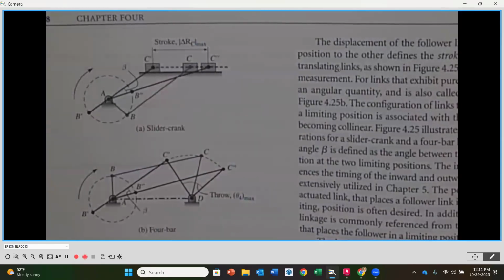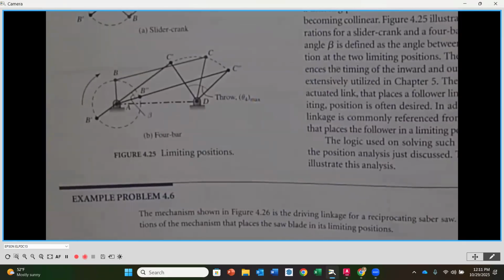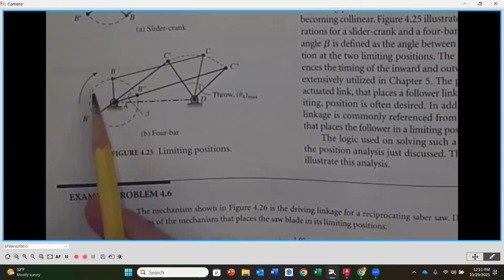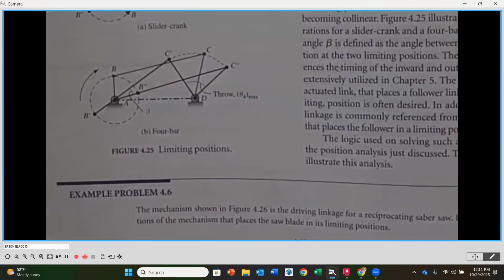When we have a mechanism that is, for instance, a standard 4-bar mechanism, and in this case there isn't a slider on the output, we've got a crank that goes around 360 degrees, but our output is going to oscillate back and forth. We call this a crank rocker, if you remember from Module 1. This was one of the standard 4-bar mechanisms that's out there.